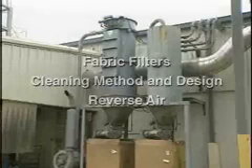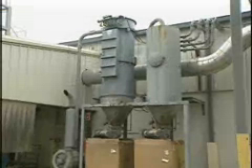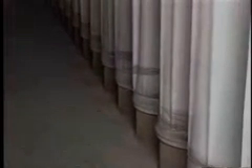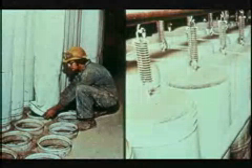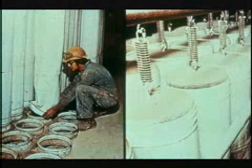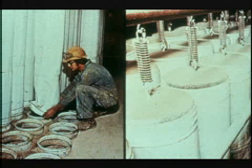The reverse air collector is very similar to the shaker collector. The collector has a tube sheet between the casing and the hopper. The bottoms of the bags are attached to holes in the tube sheet. However, the closed tops of the bags are attached to a support structure in the top of the casing that holds the bags under tension.